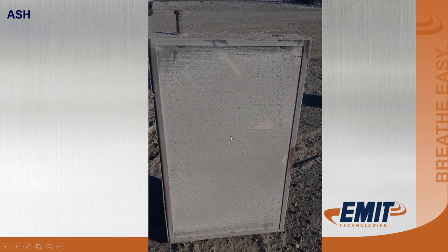Here's another unit. This was a 399 Caterpillar. Unit was not meeting emissions. Customer called us out and said they had put new catalyst elements in it. Well, they put new catalyst elements in it right next to this one, and so this one was very plugged. Obviously, that's just simply ash, and you can most of the time salvage these catalysts if they haven't been over temped or they don't have a ton of years on them.